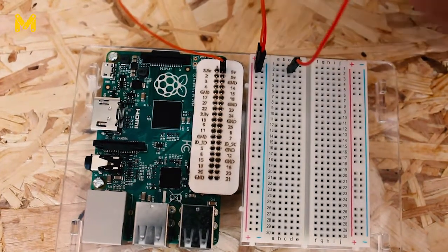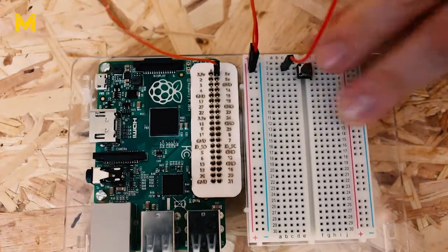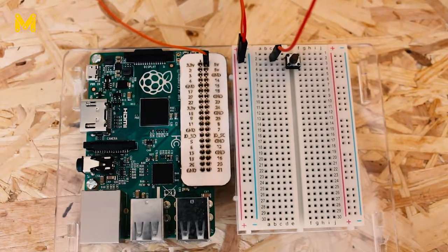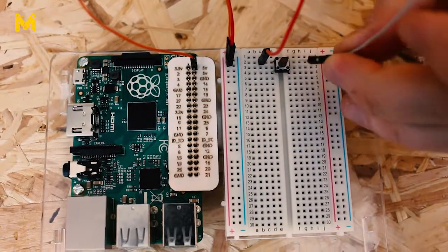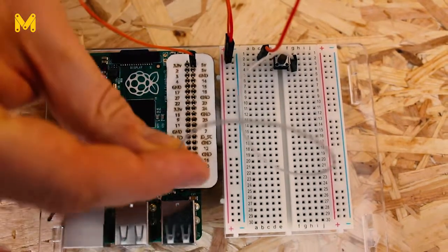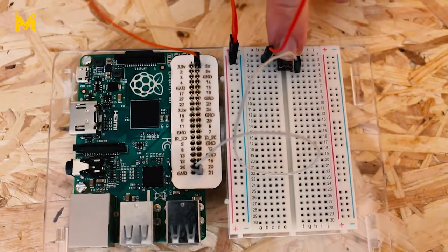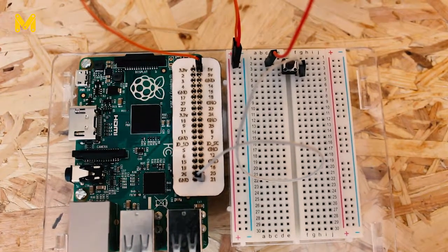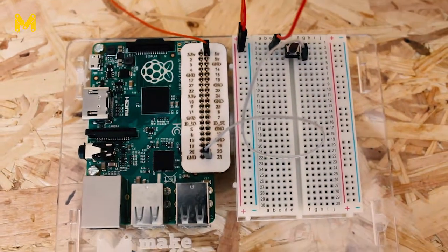I'm then going to take my switch and I'm going to bridge it across the trench so that the electrons can flow when I press it. And I'm then going to do something a bit different this time. I am going to take one of my male to female jumper wires, and I'm going to take it from the bottom leg of the switch, and I'm going to pin it over pin number 21, so that when the electrons flow through the circuit, some of them will go down to pin 21, and that will give us an input.